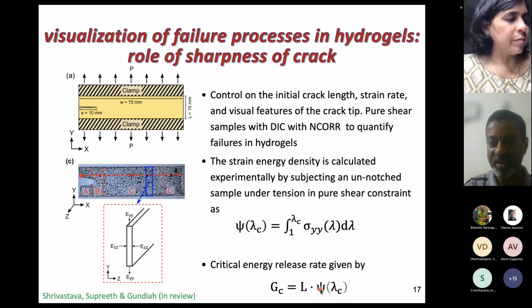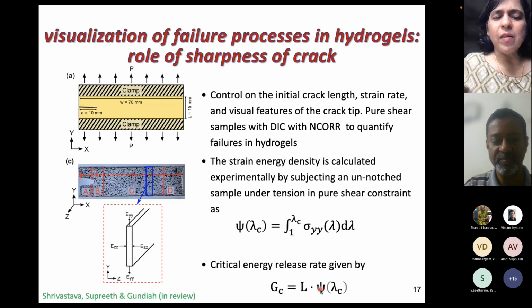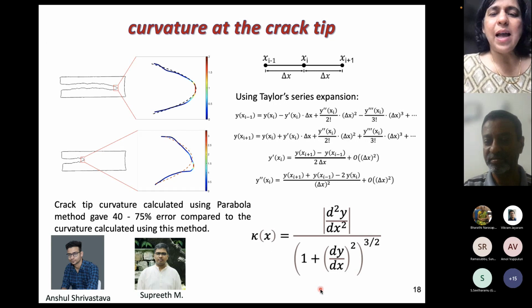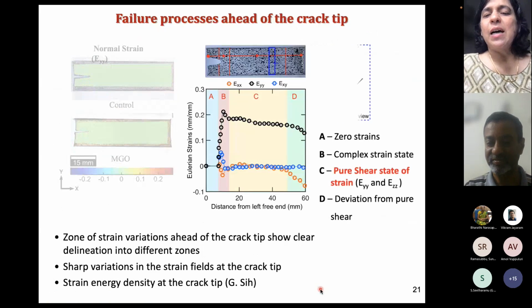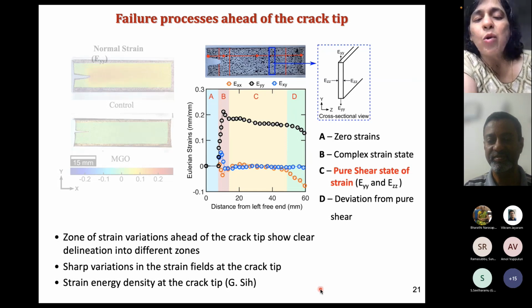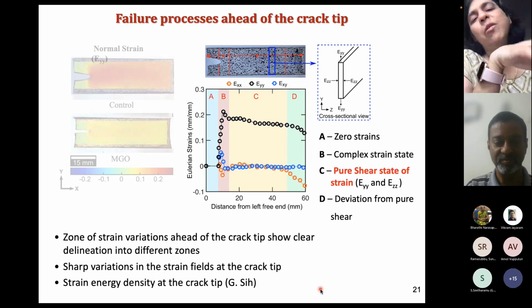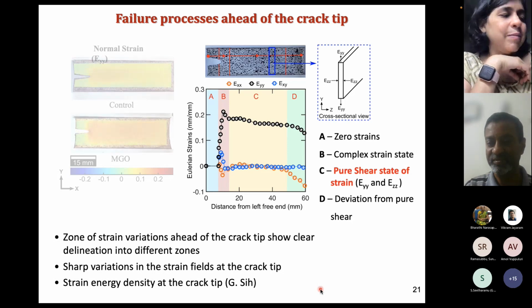Okay, thank you. I think the next one is the same. Yeah. I think if it is mode 1, it is a pure normal test with the DCB test. Yeah, so I think again, those are similar questions on the pure shear. And I think again, this slide should help clarify why it is called a pure shear, or also this picture that shows where the pure shear is valid. Otherwise, it's confusing because it looks like a mode 1, but actually the pure shear is introduced in the YZ direction. And what you're viewing from above is the XY plane, which is why this confusion arises, I think.